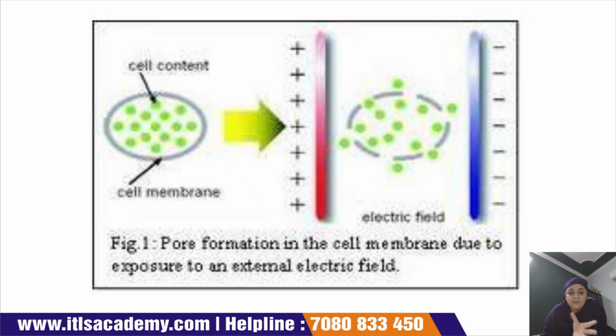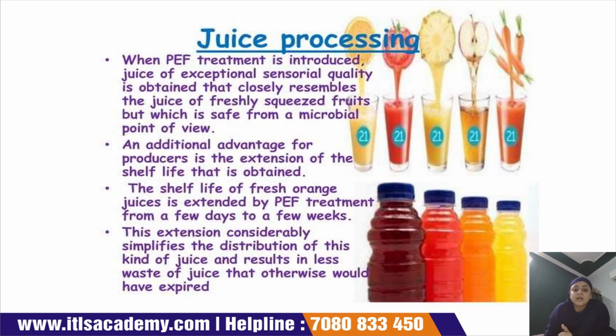So this is your cell membrane, then we apply the electric field, and pores form in the cell membrane due to exposure to the external electric field. Now for juice processing, when we apply pulse electric field treatment, exceptional sensory quality is obtained that closely resembles the juice of freshly squeezed fruit, but which is very safe from a microbial point of view.